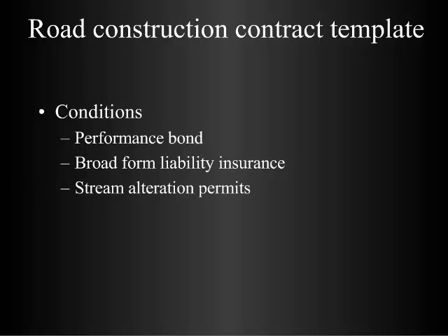Stream alteration permits. If the job crosses streams, springs, or rivers, and you have to do anything within the ordinary high water mark of the streams, you need a permit. I'm going to cover that in another little section in a few minutes. The problem with these permits is they say they'll have them back to you in 40 days, and we've never gotten one in 40 days. We just assume after 40 days that the project's approved and move forward. If it's going to be a time-sensitive project and the landowner wants to get that permit ahead of time to save time, that's great. If not, they may put the responsibility on the contractor to get the alteration permits.